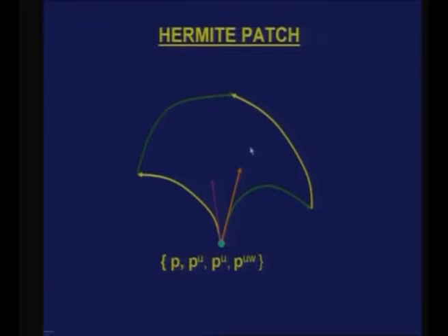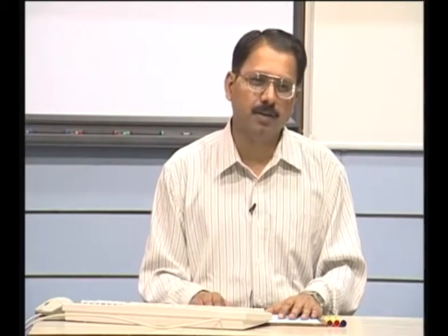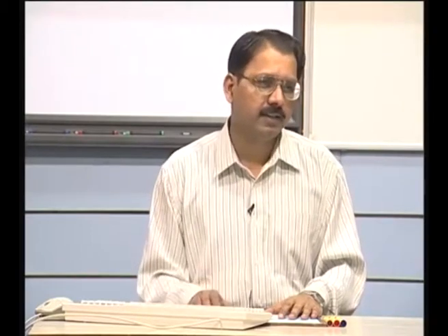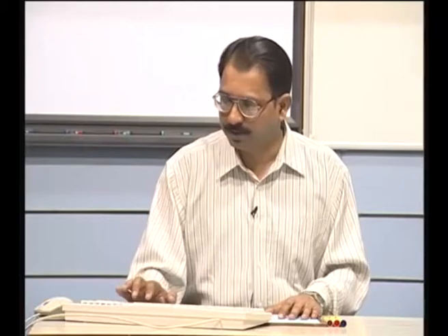So, this is a better form than the algebraic form, because if I want the surface to have a certain tangential direction at any particular point, I can make it happen, or I can also specify twist vectors at corner points.